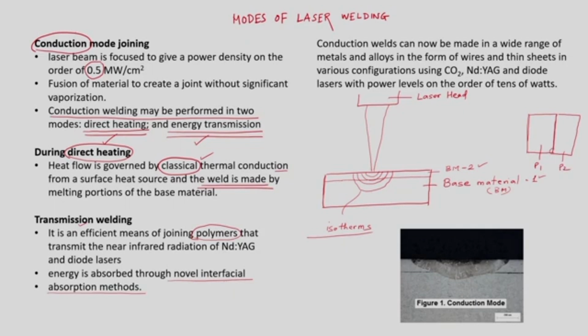The laser will be applied, there would be generation of weldment, and then we keep traversing the laser beam. We scan the laser beam either in pulse mode or in continuous mode along the path where we need to join these two materials. This is the path along which we simply move the beam.